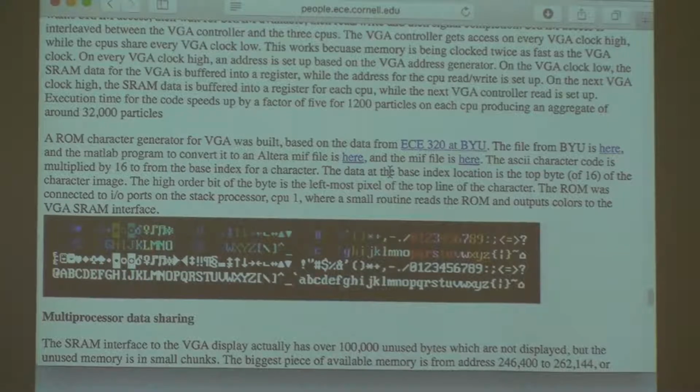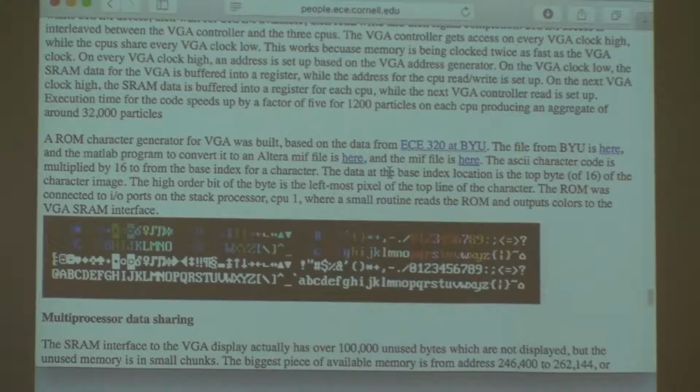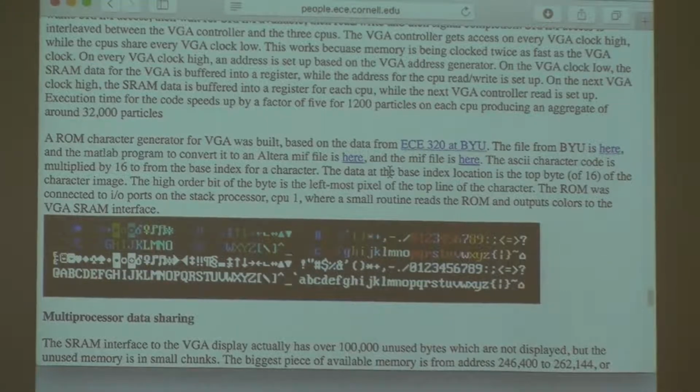Now, an interesting question is, since the HPS character overlay is a separate module from the VGA, could you feed the character output from the QSys bus into your custom VGA adapter? I do not know. I haven't tried that. That'd be interesting to try, because then you could use the HPS to just draw the characters as an overlay.